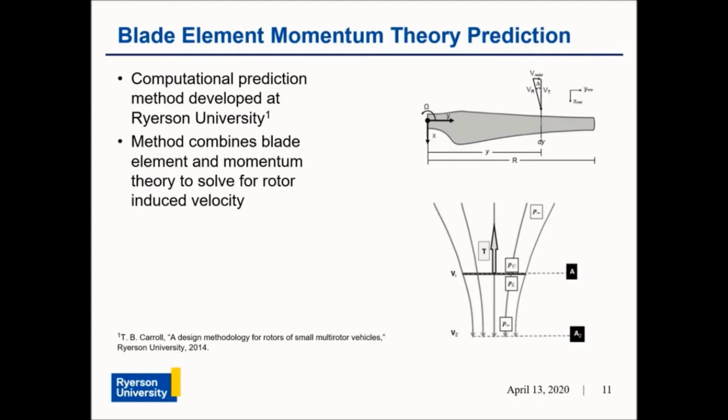To determine the airfoil section aerodynamic characteristics, a table lookup scheme was used. The tables consisted of sectional aerodynamic coefficients that were generated using experimental and 2D prediction methods such as Xfoil. The computational method took in inputs for the angle of attack and Reynolds number, and using these input variables, the table lookup scheme was executed and the sectional aerodynamic characteristics were found, which were then used to find the rotor forces and moments over the full rotor disc.